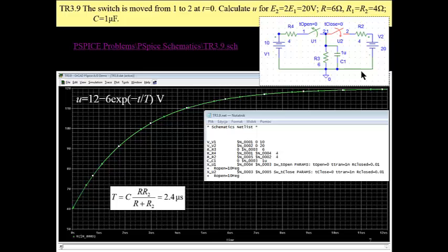When the simulation is completed, we may add a trace, and this trace is the voltage. We have to extract the schematic netlist to examine what the number of this node actually is. This number is 3, so our trace is the trace of V at node 3. Okay, very briefly let me repeat this simulation live.